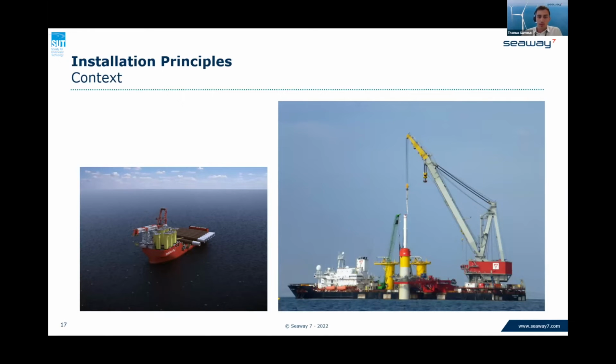So focusing back on bottom fixed foundations and the installation principles behind them. Our inputs may include the vessel type when thinking about an offshore wind farm, whether it can be jack-up or a floating vessel, the motions that come with it, the deck space you've got for all the equipment, and then the crane capability, so the load and the radius.